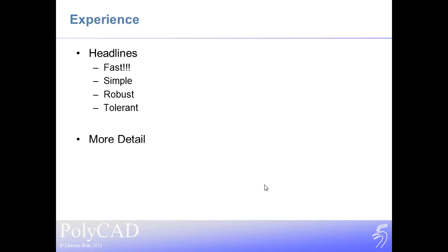If we were to look at the process in more detail, we see that this, compared to the surface approach, is global interpolation, which is quite interesting. It means that curvature is being maintained as being smooth across all of our curves if we allow it to. This is unlike the surfaces in our previous example, where the blending only takes place between local curves, and fundamentally it's local. So we're relying on the software to match the curvature between those surfaces, but cubic blending doesn't match curvature, it only matches tangency. So there's quite a discrepancy between the kind of smoothness that we'd like to get from our surfaces, which we're limited to because of the local interpolation. But the curve method can smooth that curvature around because it uses global interpolation.